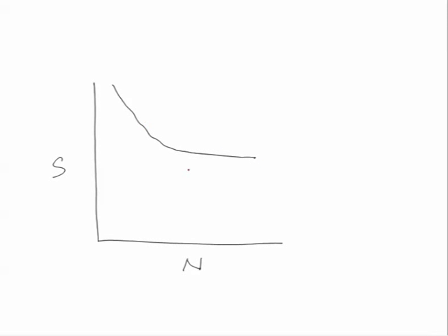To understand this in a better way, we can see this diagram here. For the fatigue life, basically we use the SN curve for the steels, this SN curve, this is log scale. Here it shows that with the reduction in the stress amplitude, the number of cycles increases, and here N stands for the number of load cycles, and S is used in a number of ways. It can be stress range, maximum stress or the stress amplitude.